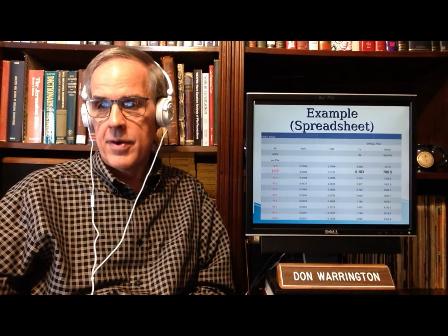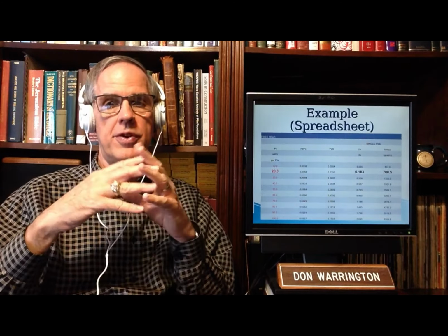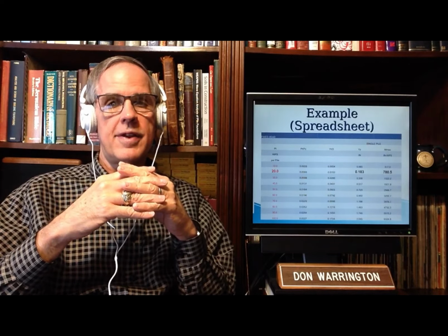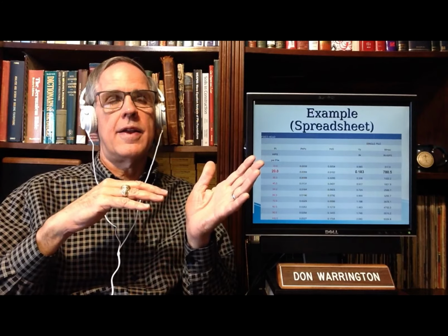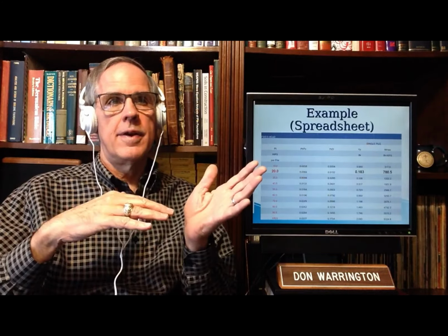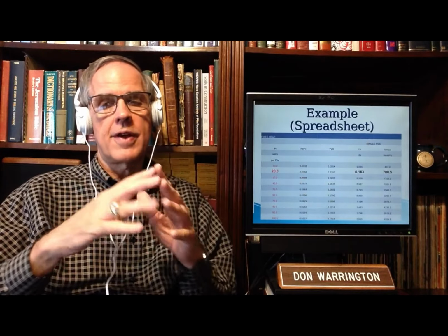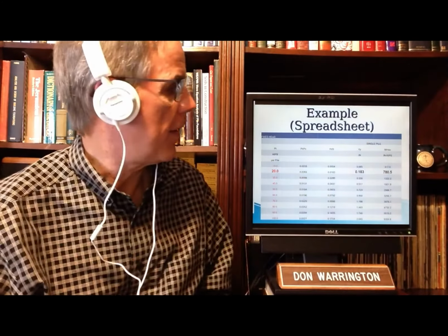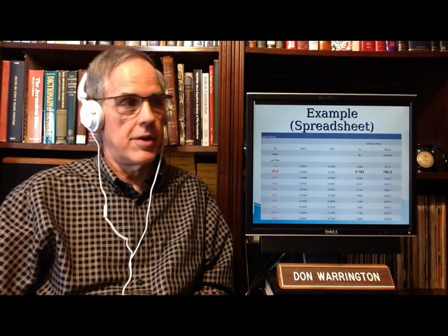Once you do that, though, and you pick, now the spreadsheet itself has several results, and I would suggest before you start playing with it that you look at the little document that came with it. You'll quickly see that you've got fixed head and free head and combined moment and shear force for free heads. I think those are the three combinations the spreadsheet will analyze. This is the fixed head part, and it'll give you all these tables. Make sure you pick the right one when you actually pick the solution.